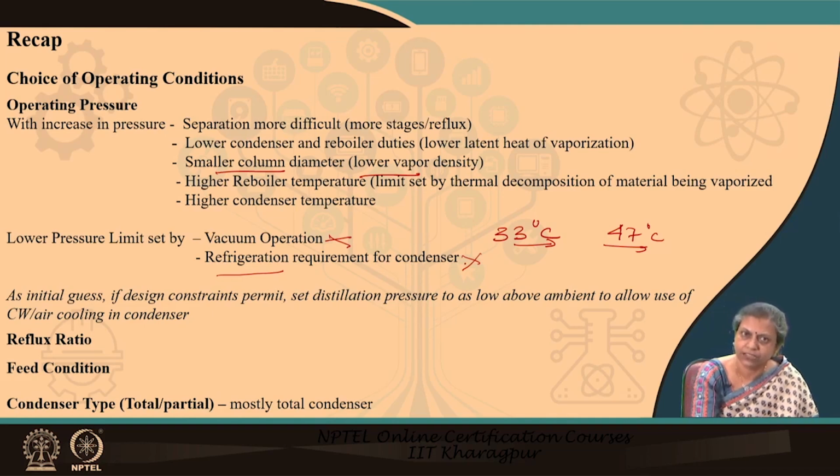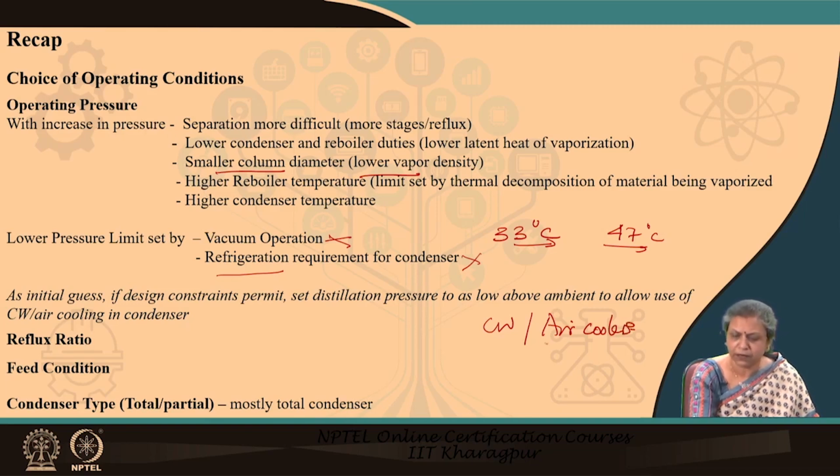It will be absolutely essential, suppose it happens that we would like to use either cooling water or say air coolers, and we find that for using these we have to go for a combination of high pressure operation and using of refrigerants. It can also happen that the top product decomposes or deteriorates or cracks at the temperature of the condensate. Under that condition, in order to reduce the temperature, we would prefer a vacuum operation.